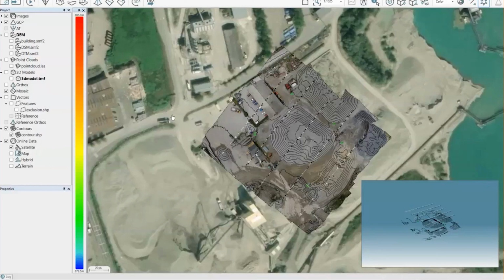So what we can sometimes suggest, if you want to quickly get data going into Correlator 3D, is you can manually run your AT, so doing the type 1 extraction and the bundle adjustment. Then you can review your AT results, so you're sure that the quality reports and the solution meet your project needs.